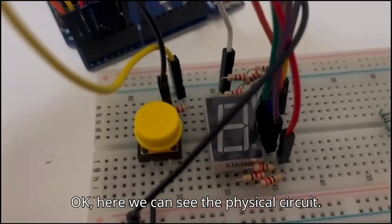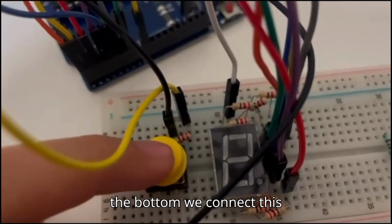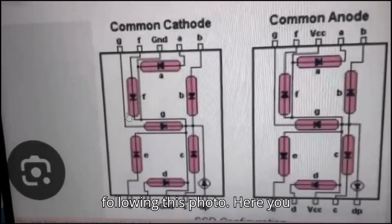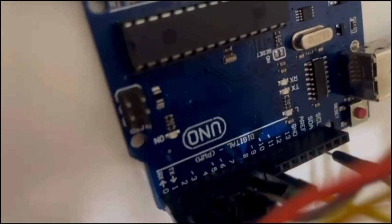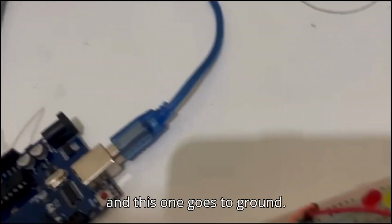Okay, here we can see the physical circuit. Here we have a 7-segment display on the bottom. We connect this 7-segment display following this photo. Here we can see the order, and we connect with resistors. All these resistors go from pin 0 to pin 6, and this one goes to ground.